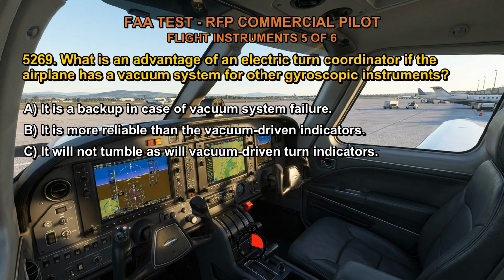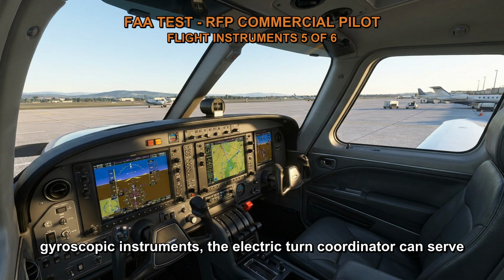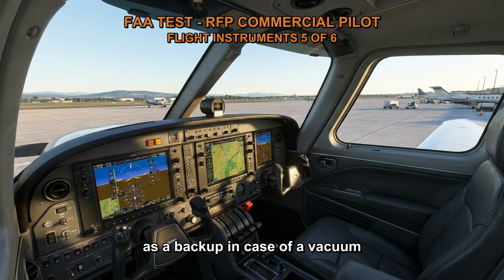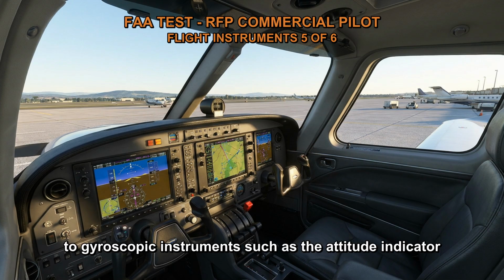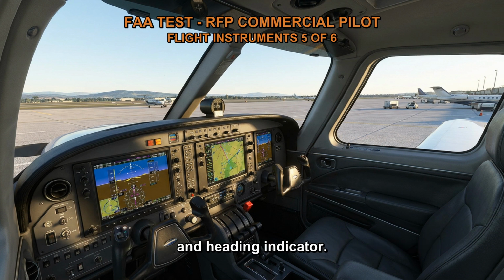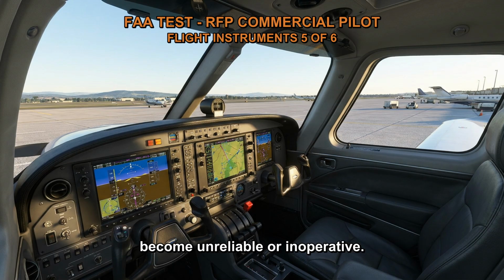The correct answer is A. In an aircraft equipped with both an electric turn coordinator and a vacuum system for other gyroscopic instruments, the electric turn coordinator can serve as a backup in case of a vacuum system failure. The vacuum system is responsible for providing power to gyroscopic instruments such as the attitude indicator and heading indicator. If the vacuum system fails, these instruments may become unreliable or inoperative.